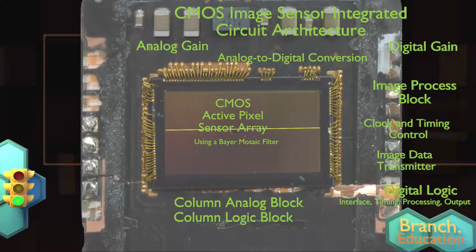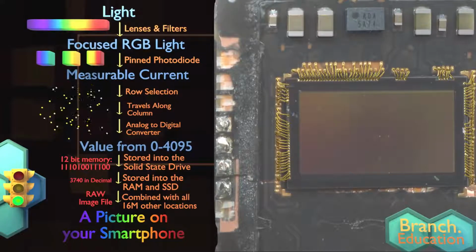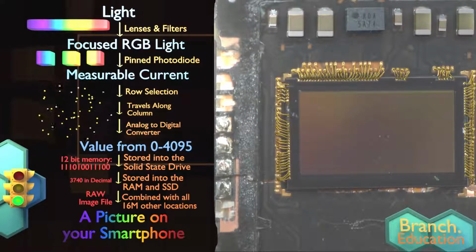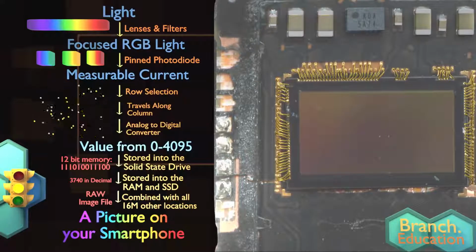A rolling electronic shutter is timed with the row value reading in order to turn off the sensor's sensitivity to light. The analog to digital converter interprets the buildup of electrons and converts it into a digital value from 0 to 4096. This value gets stored in a 12-bit memory location. Once all 2,998 rows totaling 16 million values get stored, the overall image gets sent to the CPU for processing.